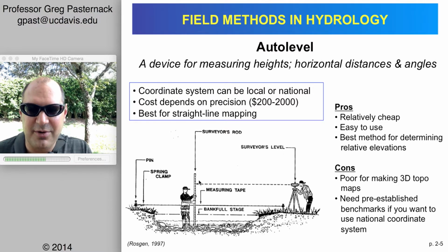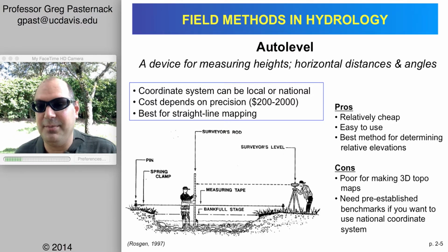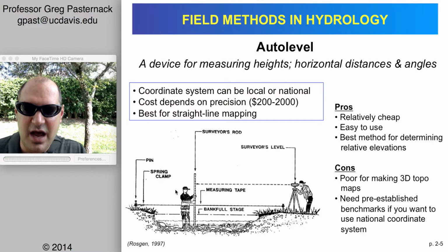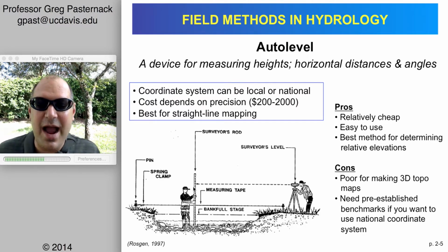So let's say this is 8 out of 10, whatever units they are. Now when the person comes up on the bank and you go to that same horizontal position, well, since they're up, the rod is going to be up higher, which means that the telescope will be reading off a number closer to the bottom. So actually, the higher the ground is, the smaller the number will be. So that's how it works in practice.